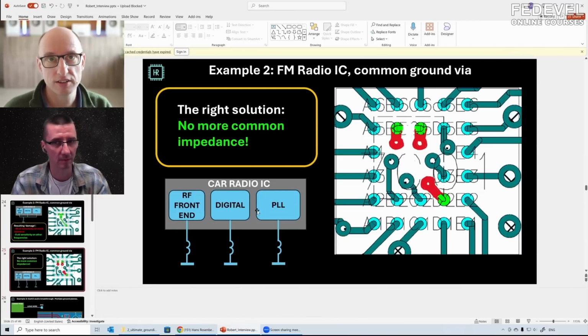And the thing is, and that's kept striking me during my career, that these were not really dumb people. I mean, these were really smart engineers, but this grounding is such a bit of black magic that this goes wrong. This went wrong very often. And the solution is very simple. So this was a violation of the rule: give each pin its own via.